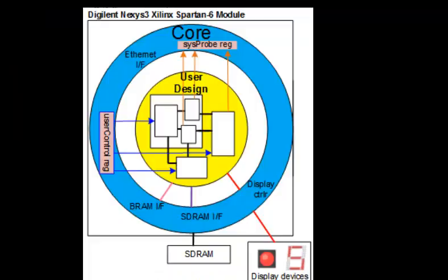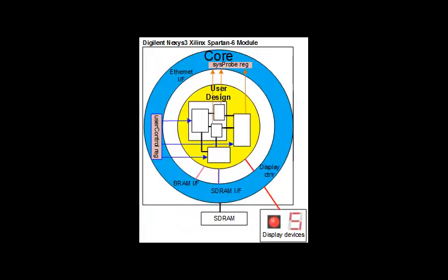This application takes the m21.vhd and it connects it to a core. The core has an Ethernet interface which communicates to and from the web application. The core also has other elements such as display controller and registers for input signals and output signals which relay the signals inside designs to and from the web application. The process of linking to the core and connecting signals from inside a user design to the core is automated.